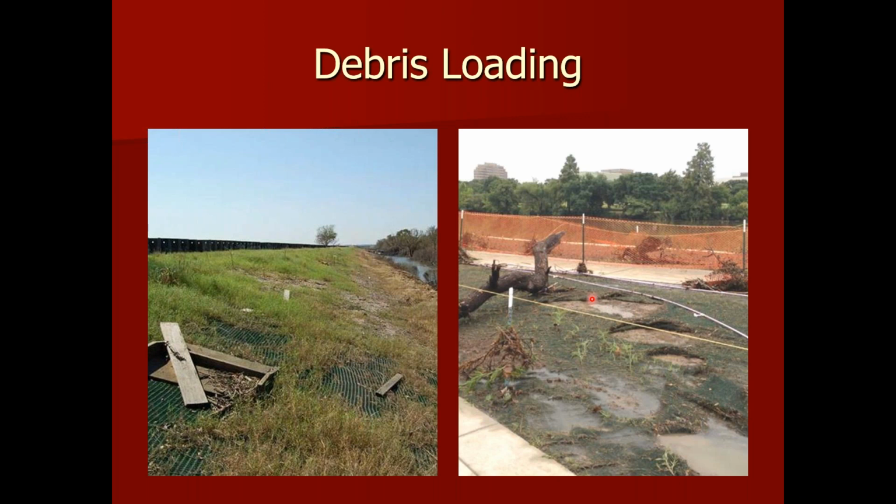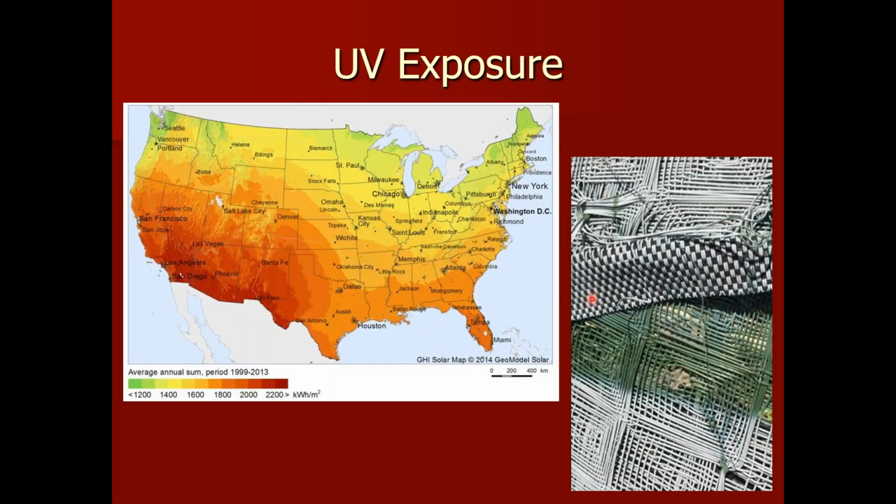Any flow now that would wash across that system would get underneath the TRM and cause significant damage to the soil underlaying the system. So the strength of that TRM is extremely important, mainly before the vegetation is able to take hold. UV exposure is very important.